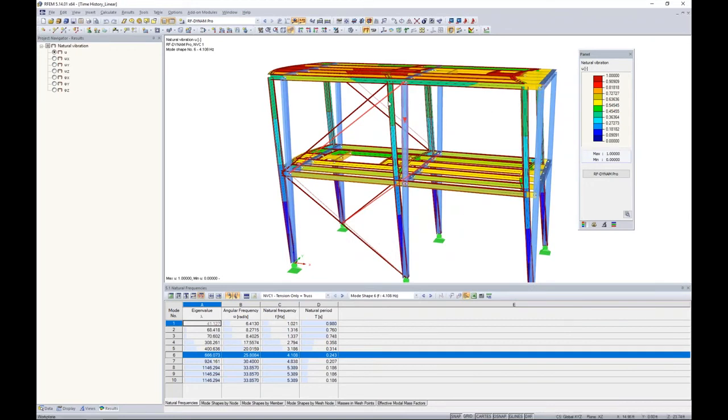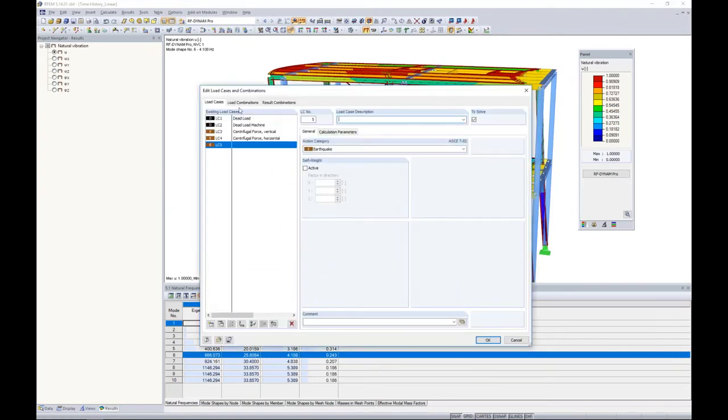So what I'd like to do is to completely deactivate them and to rerun my natural vibration analysis. So how can I do that? Well, back in RFEM, I'm going to create a new load case. Now, remember, load cases are something that I apply my dead loads to, or I applied my centrifugal forces to. Well, for this 5th load case, I'm going to call this one tension-only deactivation. And I'm not going to account for self-weight.